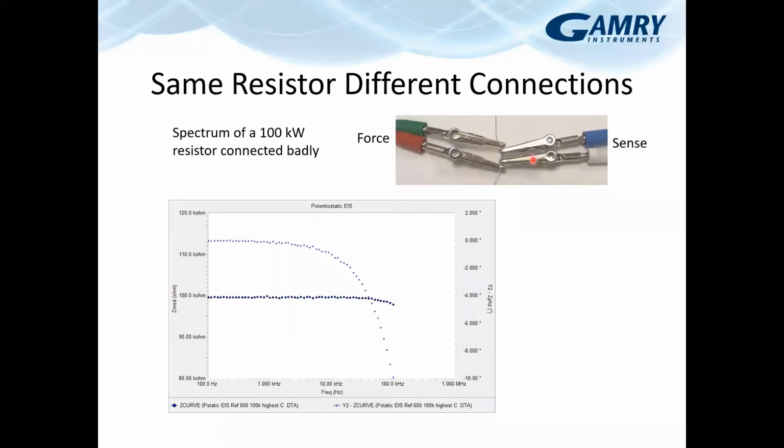So if you bring all those cables together and they're all aligned, oriented in the same way, you're going to maximize the amount of capacitance that you're picking up across them, and you're going to introduce greater phase errors than you will if you can orient them differently.